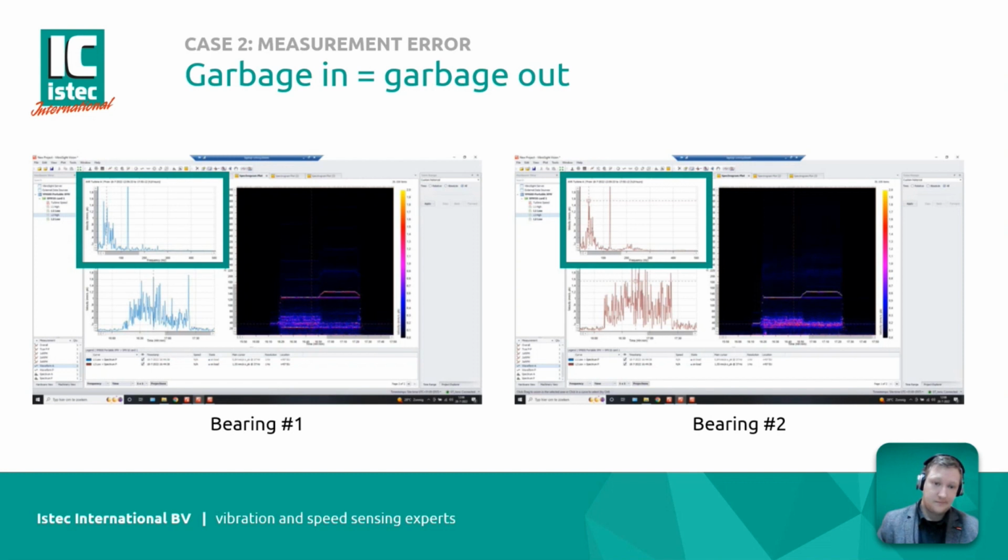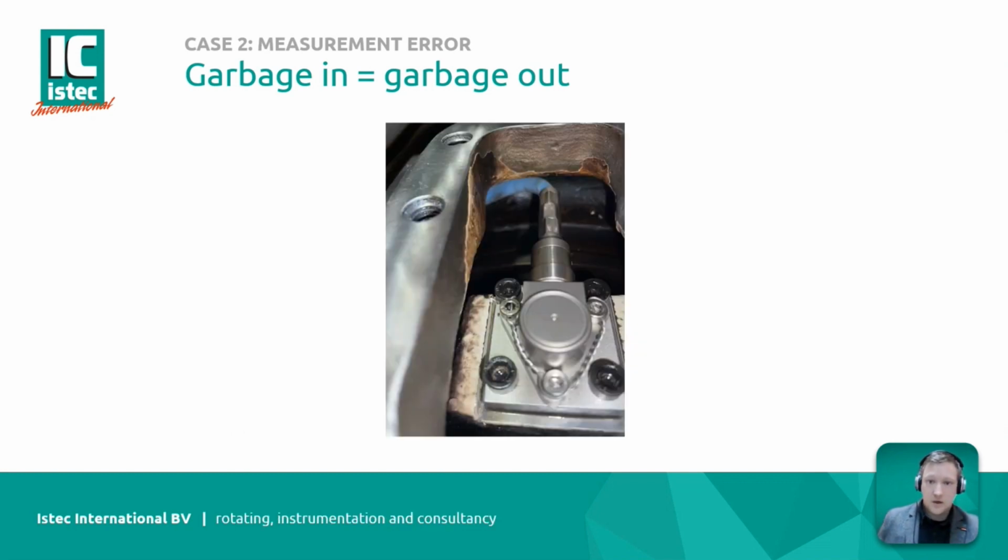And in vibration theory, when it comes to flow turbulences, it's an example which looks like this. So you can easily think, oh, there is an issue with my flow. But when it was inspected, it was found that the sensor cable was touching the casing, and that was introducing a grounding issue.